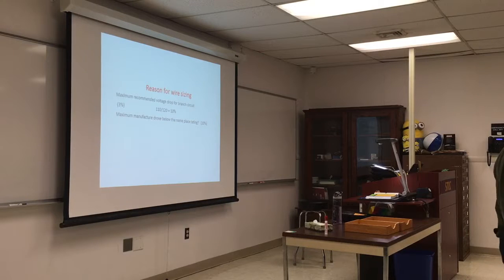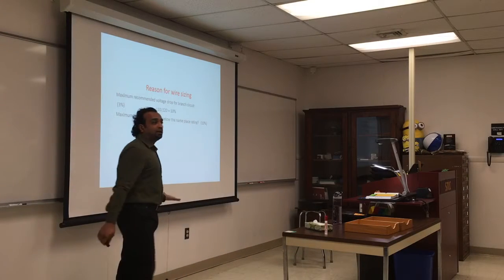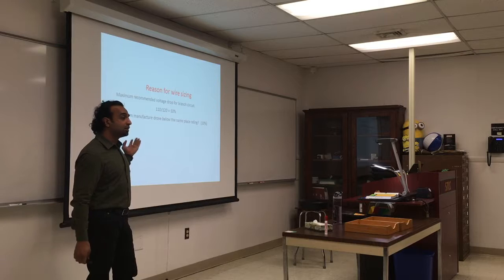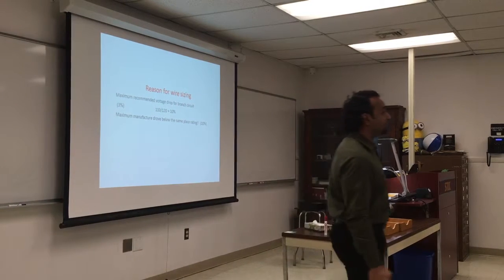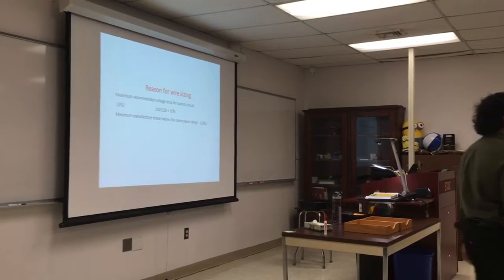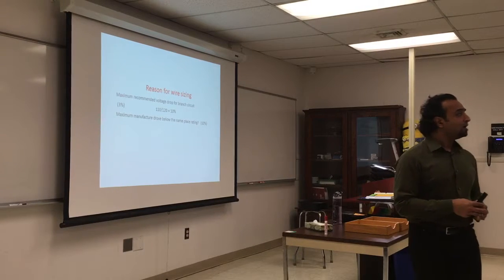below the nameplate. What is the nameplate? It's what is labeled on the equipment. If it says 120, only 10% is the maximum. If it goes lower than that or higher than that, probably the equipment is not going to run properly. Again, a lot of time these things are neglected, and it's something you should check at some point, especially for a new installation, or if something has been added to the equipment. Think of that voltage drop.